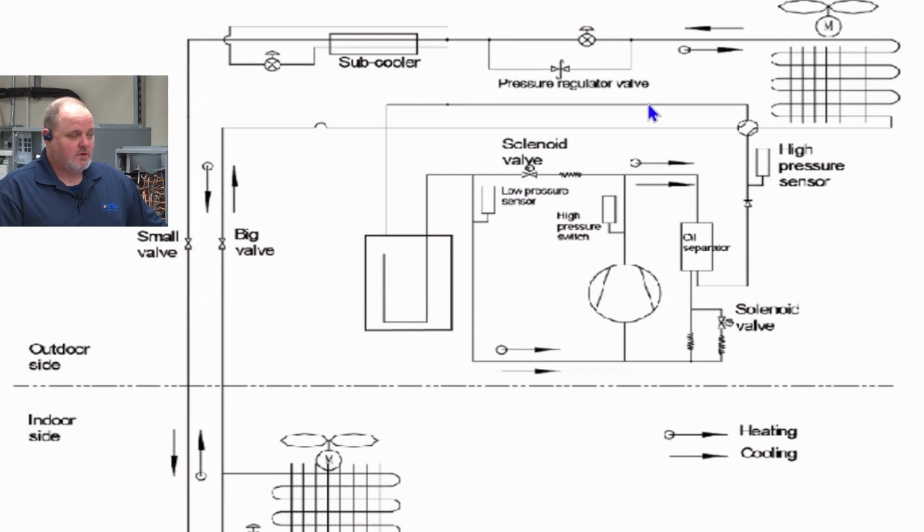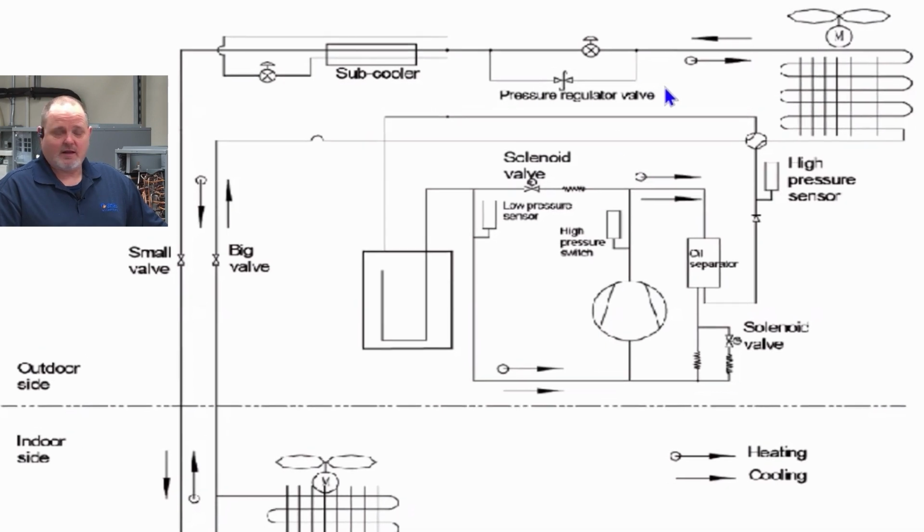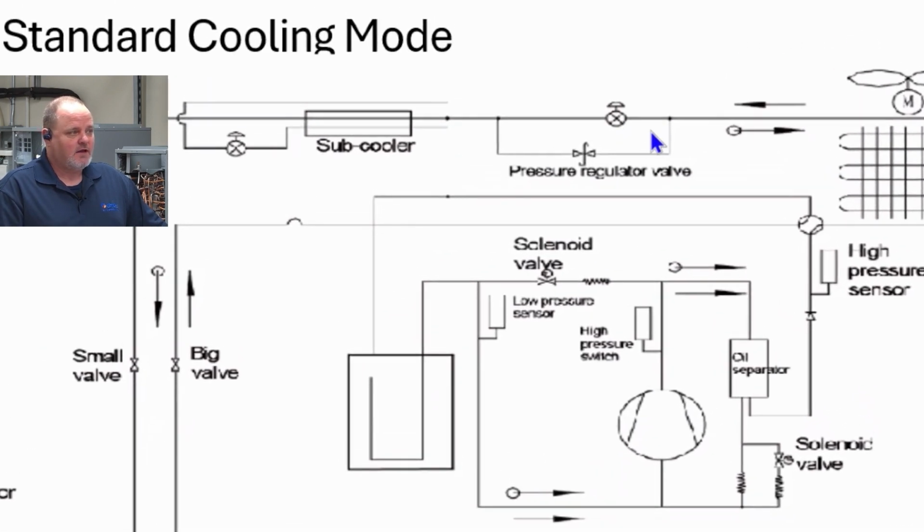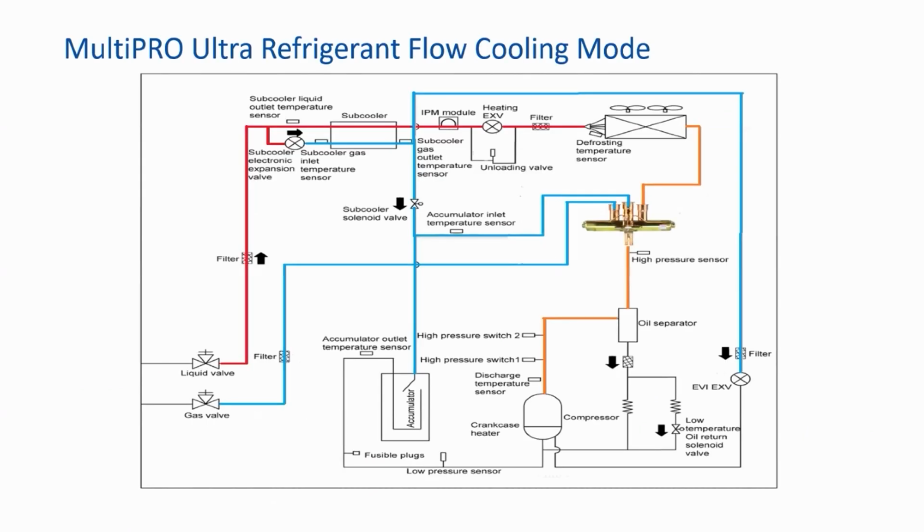Once he took the side panel off and I told him to look for these EEVs, he found that coil just hanging there. We put the EEV coil on that valve body and had that machine up and running with no issues. So doing a simple inspection would have solved that. Right. Yeah. So this piping diagram, I want to talk about this some more as well.